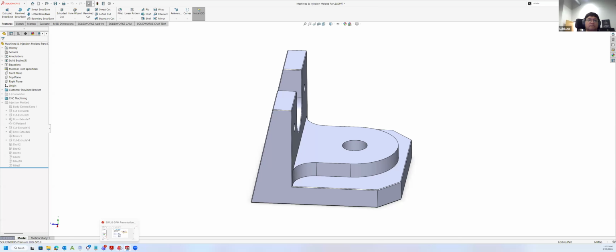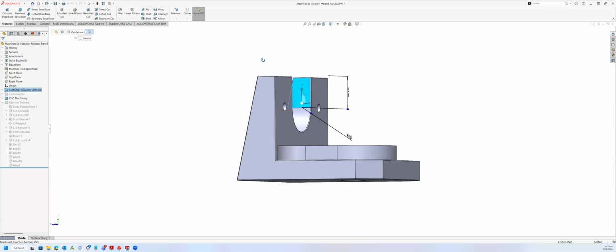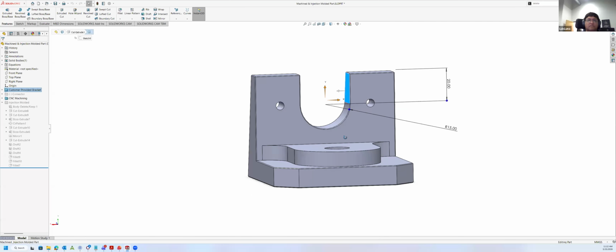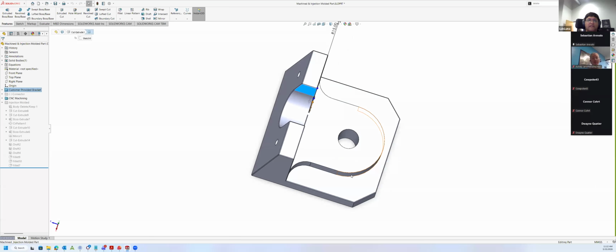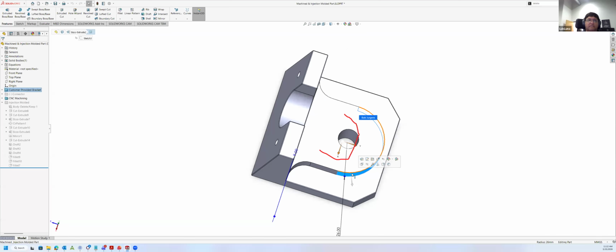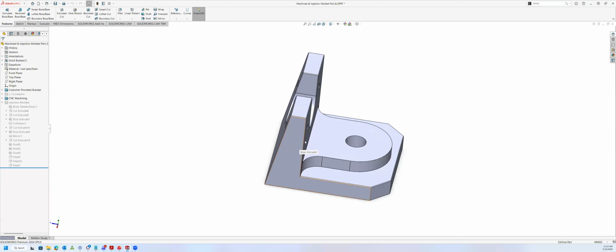Is there any requirement for that kind of circular boss, or could it all just be square on the bottom? This? Yeah. Couldn't that all just be one big flat instead of a stepped area there? Yeah, technically you could make it one big flat. Good point. Maybe the sloped face doesn't go all the way to the bottom of the base, so you have a flat to clamp onto. That's another great point.